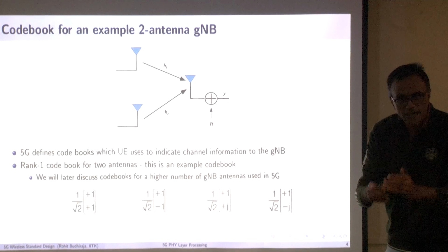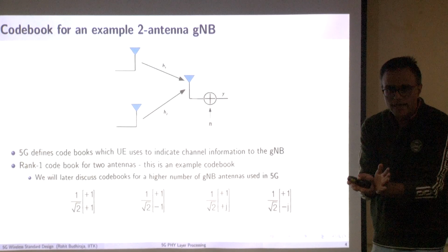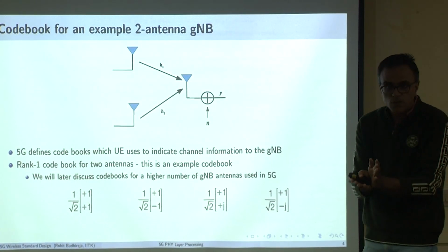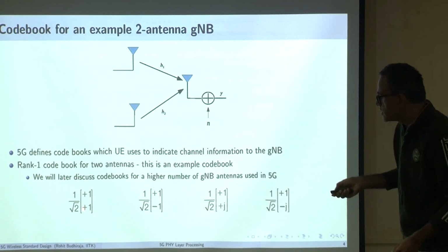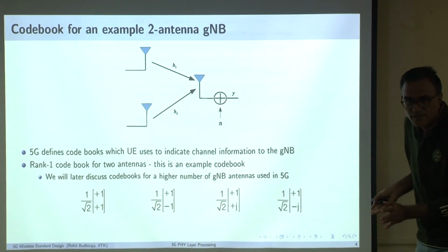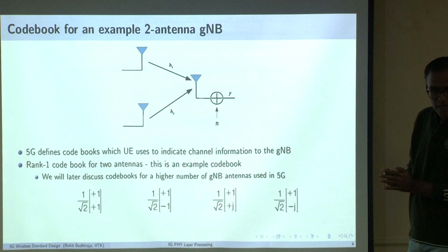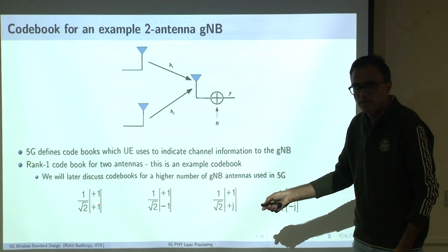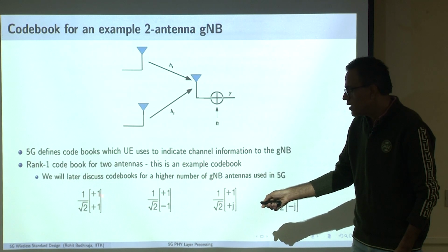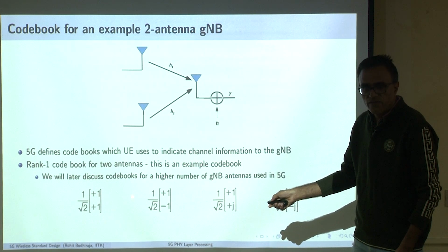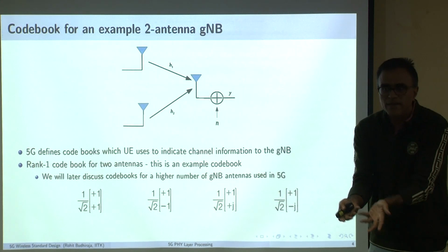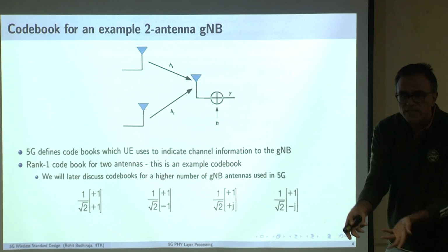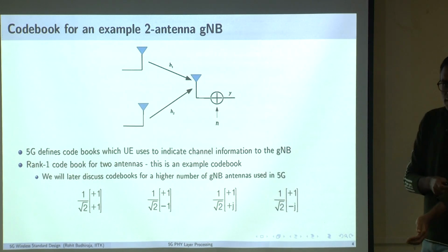But the amplitude can be different, right? If you have to send that amplitude information, you need extra bits to quantize the amplitude and then send it, which essentially means the entries will increase. For example, if for this phase itself I have to quantize 0.5 and 1, the number of entries is doubled. Instead of 4, it will become 8 entries, and the number of bits is going to increase, correct?